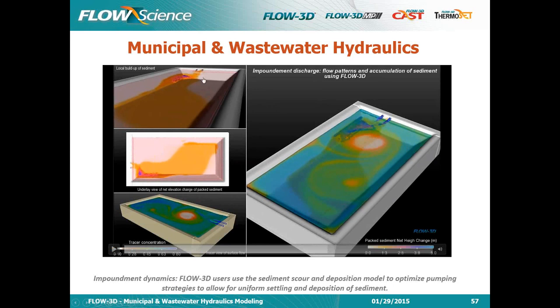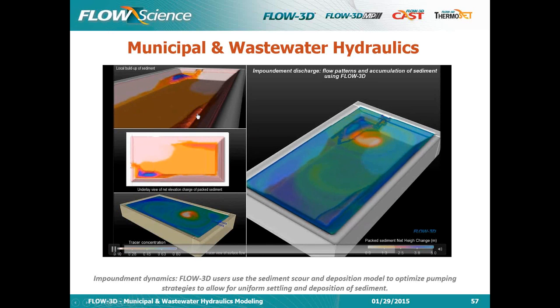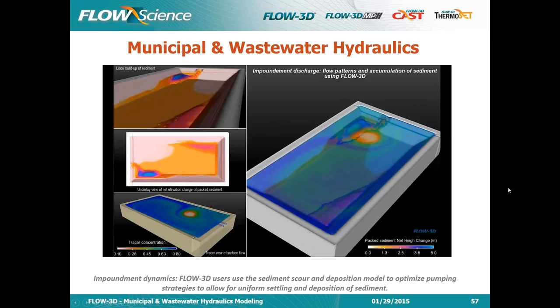I'll pause this. What we are seeing in the top left here is actually the buildup of sediment. The water is kind of transparent, and what we see is the buildup of this sediment, where you can see we have some sediments building up in this top left corner, and this is a top view. So with this configuration, this is what's going to happen if you dump this fluid into this basin for a long time. The sediment is going to accumulate here. It's also going to accumulate here, and we can see the actual buildup on this frame, and so on. So we can see where things are going to land using this model.